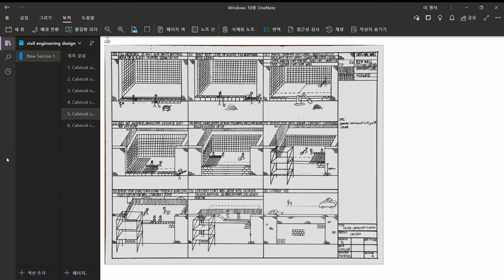with gravel. Now that the first layer from ground level has been placed, we will backfill the area behind the wall. The first 350 millimeters will be filled with gravel and the rest with on-site material. We will use the compactor to compact every 250 millimeter layer of material that gets placed, making sure that the compactor stays 1 meter away from the wall and working away from it.